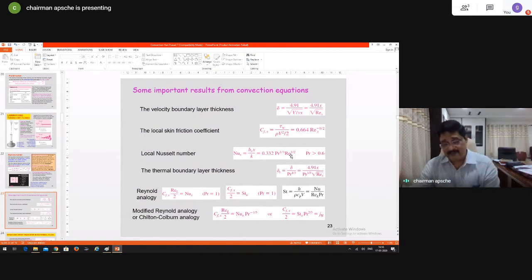What is the influence of tau, of V, of Cp? It is very difficult to understand each individual parameter, and again you need to talk about combinations of parameters. So the dimensional analysis, by the Pi theorem, helps you in grouping all the variables, and that's how we have grouped the entire force of convection into three fundamental dimensionless numbers. There may be derived numbers, like the Stanton number, which is the ratio of Nusselt to Peclet number, which is a product of Reynolds and Prandtl. All this may come, but fundamentally there are these three.